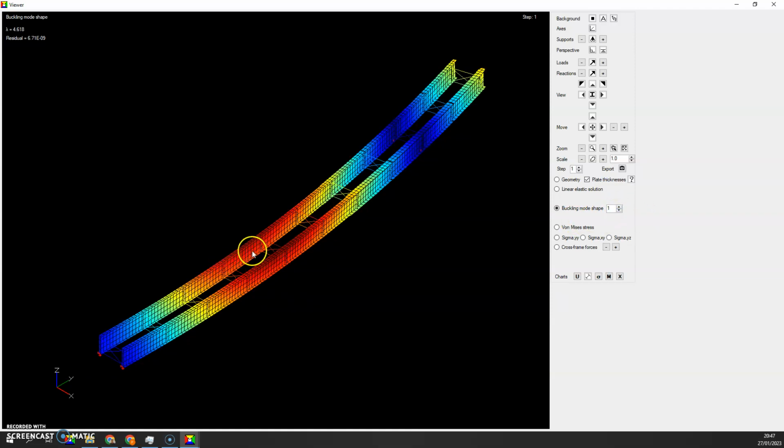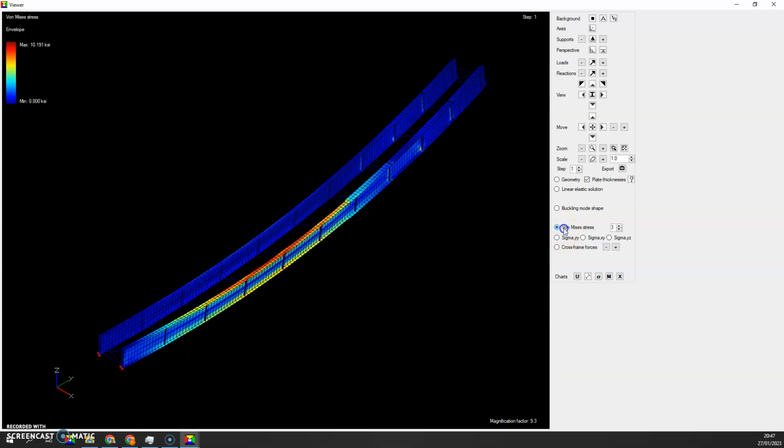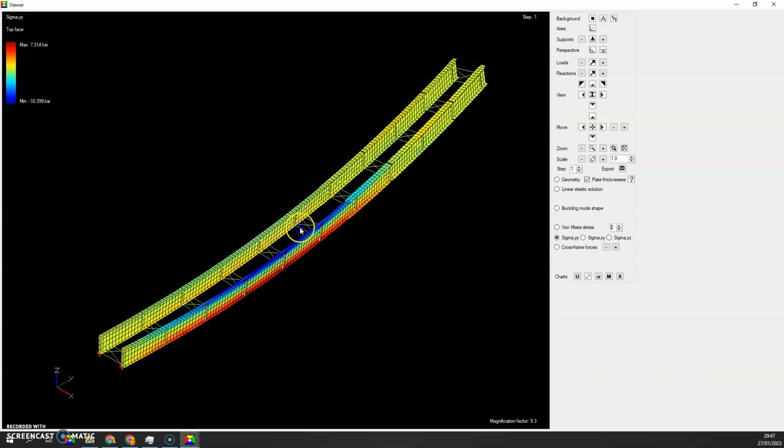We have only defined the stiffeners that we need to attach the cross frames. There may be additional stiffeners on the bridge. We can of course look at the von Mises stresses or the sigma YY stresses. So of course blue here would be compression and red would be tension here on this second girder. Actually, that's girder number 4. You can look at any other stress component, like sigma XY would be the torsion in the flanges, and sigma YZ torsion in the web.